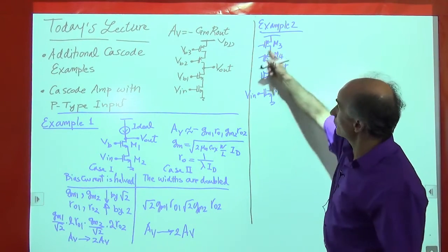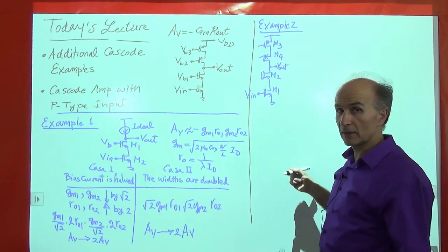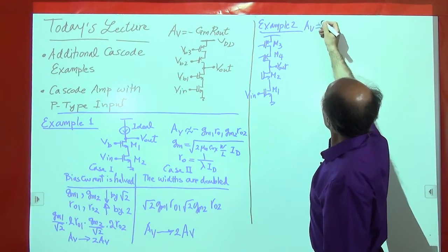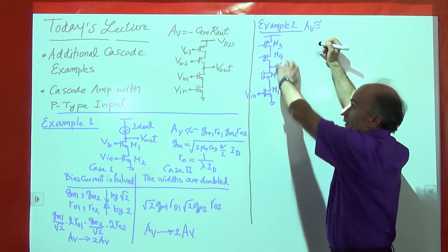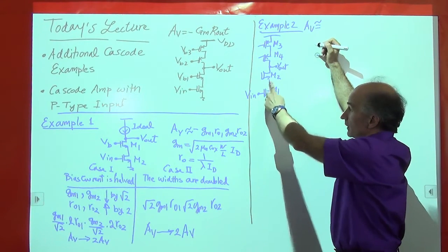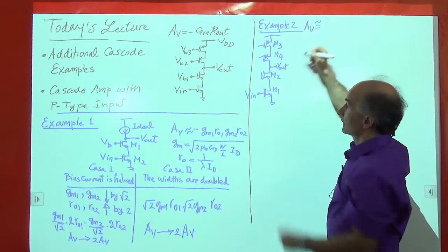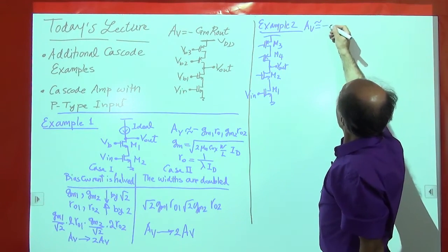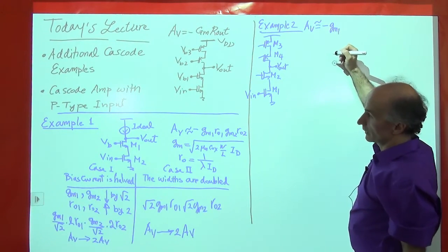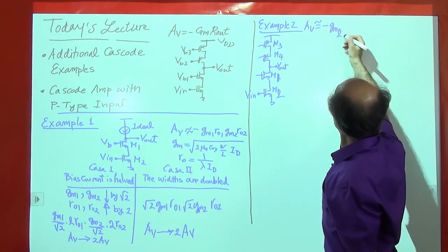I need to write the voltage gain for the circuit, and I saw that on the previous slide, in the review slide. The voltage gain is given approximately by the transconductance of the overall circuit, which is the same as that of M1, approximately, because the current generated here flows all through M2 mostly, and then flows through that short circuit. So we have minus GM1. Sorry, let's call this M1 and M2 just to be consistent. So GM2.